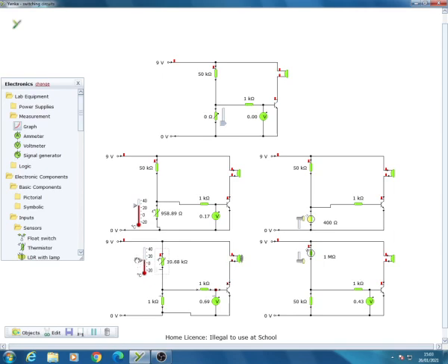So that means I can adjust the two resistances here to get it to switch on and off at different temperatures. I could do the same thing up here. That's switching on at about -10, and if I change the resistance on the thermistor, use a different thermistor, or I change the resistance on this big resistor up here, I could get this to switch on and off at different temperatures.